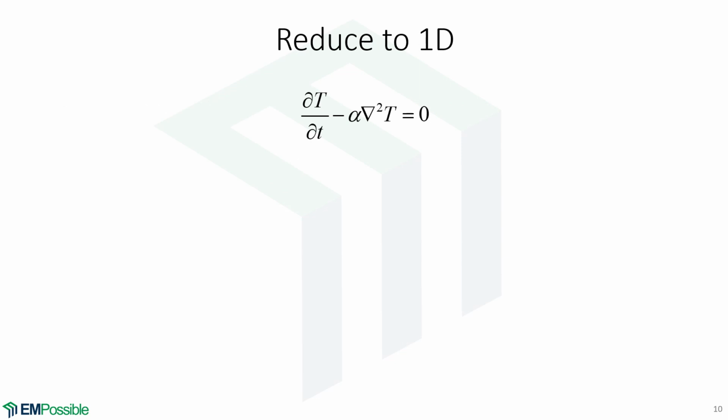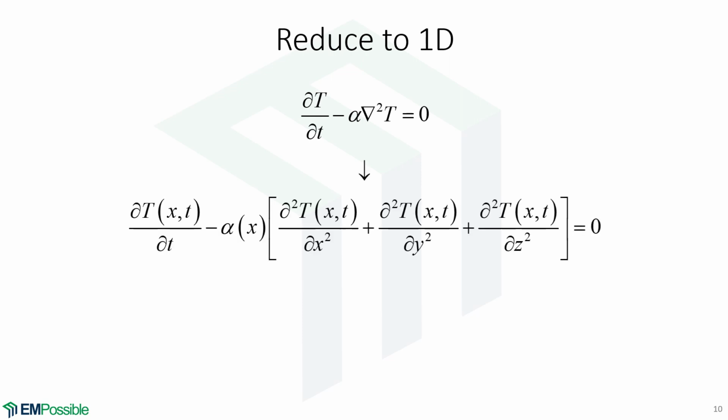First thing, we really have only a one-dimensional problem. Yes, truly it's three-dimensional because that bar has some size, but if that bar is pretty thin, typically we can solve this very accurately as a one-dimensional problem. So let's take our heat equation and expand this into all three dimensions. What changes is this Laplacian, this del squared, and that's what this expands to. It's a scalar Laplacian.